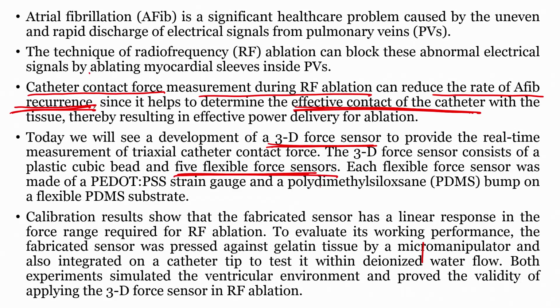We will discuss this in detail when we reach that slide, and how these force sensors are fabricated. They are fabricated by patterning strain gauges using PEDOT:PSS, and there is a PDMS bump on the flexible PDMS substrate. We will see how it works. PDMS is polydimethylsiloxane.